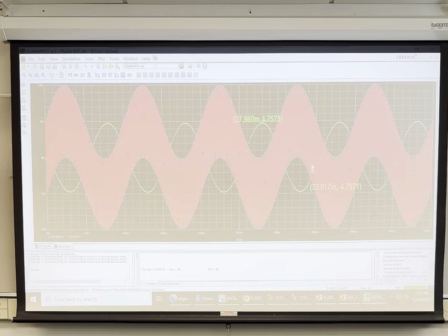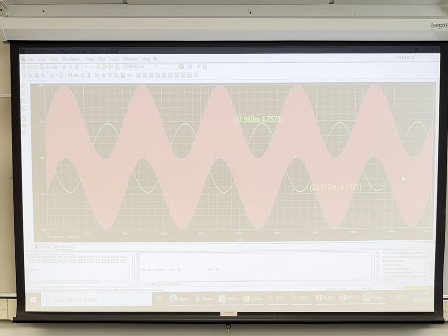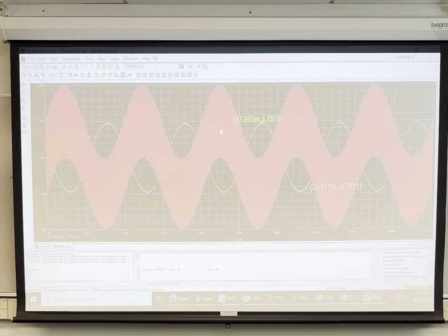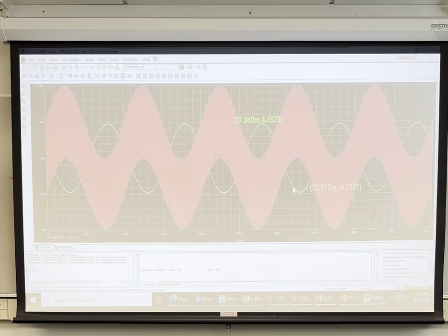What's in this larger waveform? It's a bunch of smaller waveforms. The larger one is 30. And why does it appear like that? That's the mix. The signals are mixing on the input to the amplifier. The 100 hertz is here, and the 30 kilohertz is there also. So basically, when they add algebraically, this is the way the waveform appears on the input. So the waveform is correct. You get a kind of fuzzy waveform on the input.